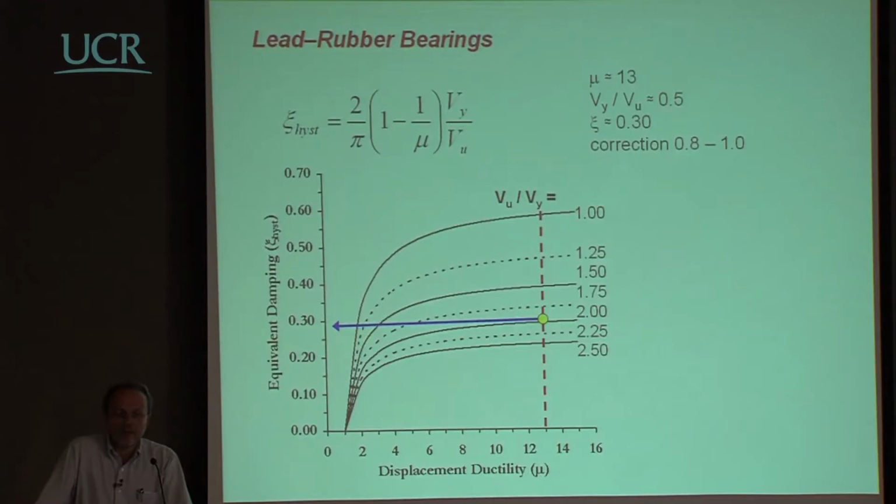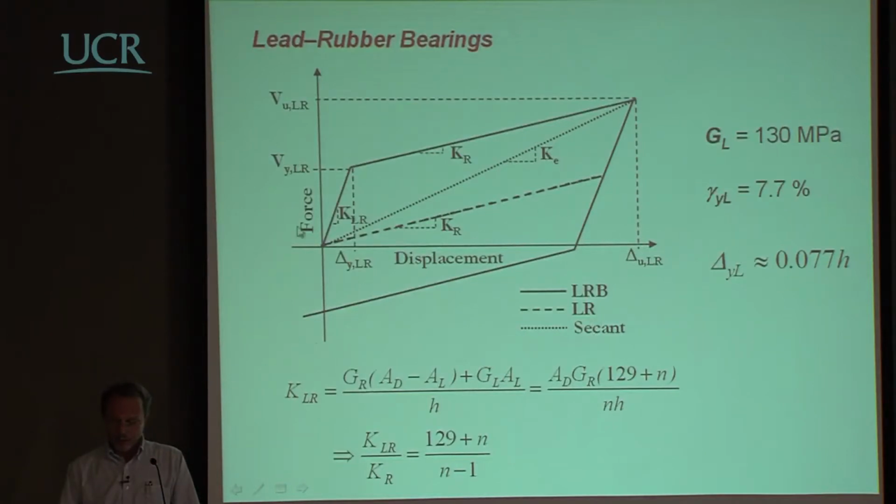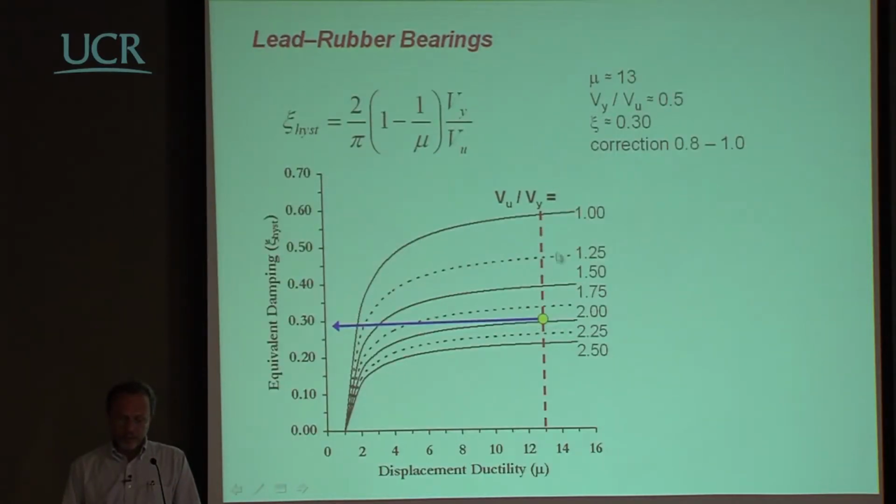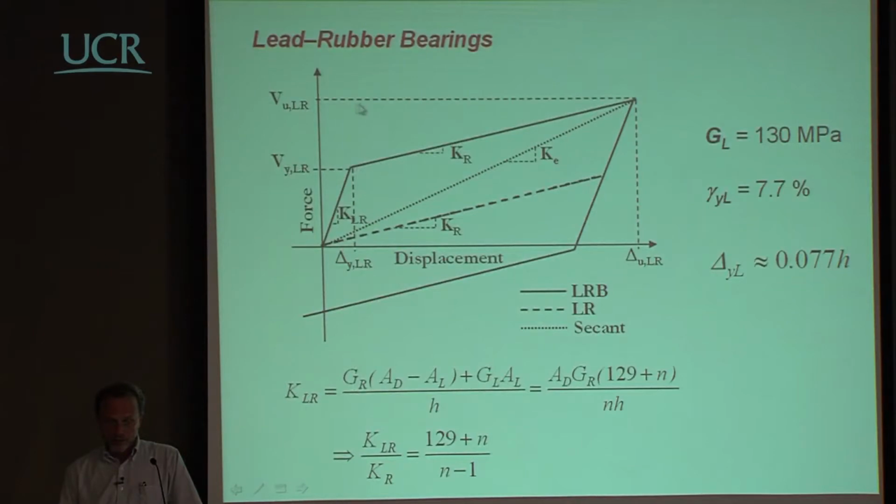But the difference now is that in the previous case, the only damping was provided by a real kind of viscous damping. And for a rubber bearing it could be in the range of, say, 10 to 17, 18%, depending on the kind of rubber. But in this case, you have this very large cycle, and therefore you have large values of equivalent damping that could be in the range of maybe 30% or so. And essentially, this depends on the ratio between the total shear that you take versus the elastic shear. So in a way, it depends on this part over this part.